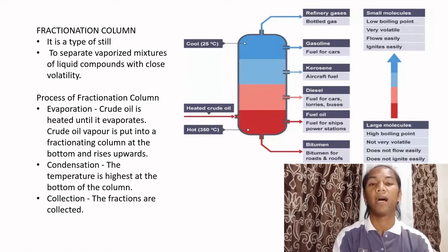So, a simple still starts with mixed liquids such as alcohol and water produced by fermenting grains. After boiling, it will produce a distillate in which the concentration of alcohol is many times higher than the feed. Crude oil is a typical feed for fractionation, and from it, the column can form simultaneously several distillates such as wax distillate, gas oil, heating oil, naphtha, and fuel gas.